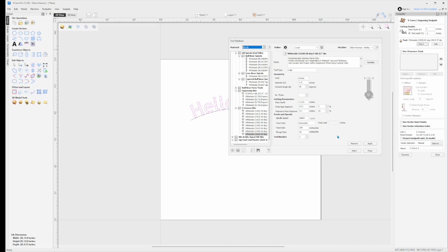One is burn. If it's moving too fast, it'll actually burn the wood, and it's hard to sand that out. As well, if you're moving too fast, it basically looks like it's unfinished, like a rougher pass. And sometimes I'll run a second pass just to make sure that everything is smoothed out.